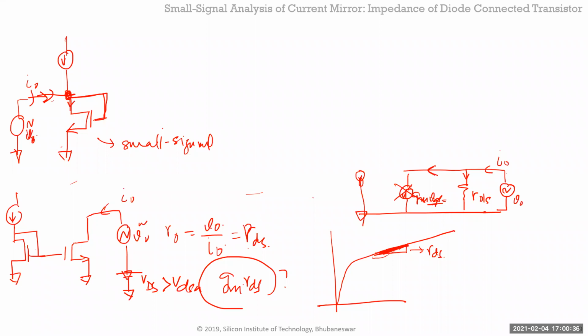You're applying this voltage here, right? So let's say you increase this by some delta V out, right? The drain changed by delta V out. So the I out flowing through this because of the RDS is delta V out by R out, right? But you're also changing something else, the gate voltage, right? But your gate voltage is huge. What is the small signal IDS current for the gate voltage delta V out? What is this current here?